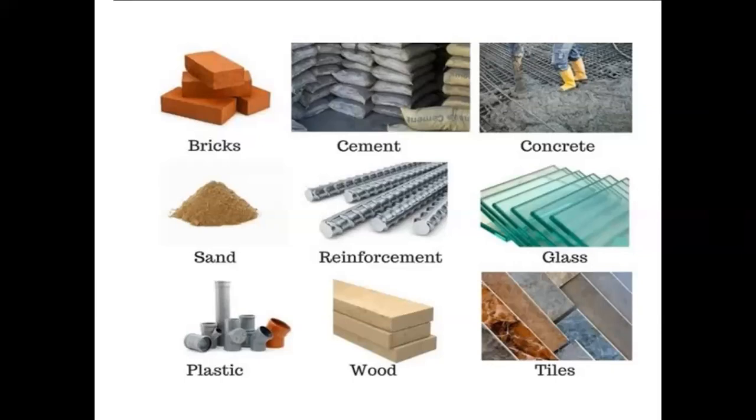Stone. Yes, stones. The stones which are present in our area. Basically, the whole of Maharashtra has a sufficient amount of basalt rock, and that basalt rock is used in the manufacturing of crushed sand. But not all basalt rocks are used. Only the hard, compact basalt rocks are used in the manufacturing of crushed sand, that is artificial sand. Likewise, the aggregates also come from basalt rock.